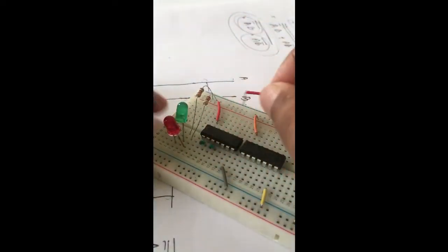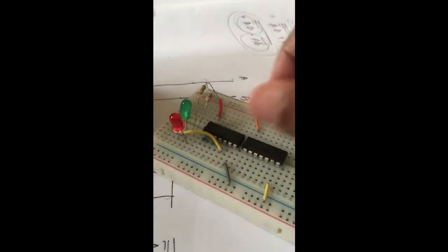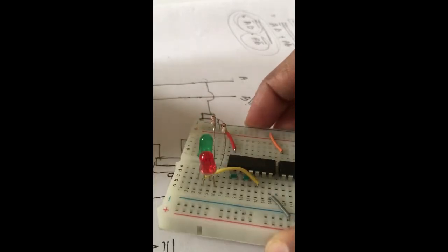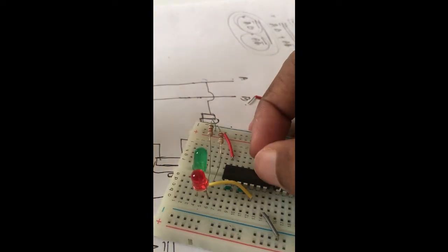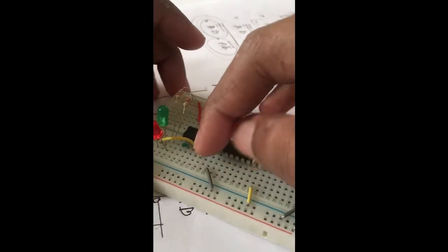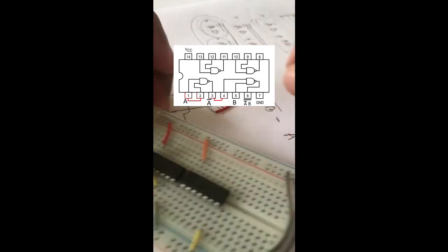Okay, this is shorter. We have to take another jumper. Okay. So at pin 5 we put B, so we get for the second NAND gate A not B, so we will get A not B whole not, and another input will be A B not whole not, so we have to put A. So from the output at 6 we get A not B whole not, right?